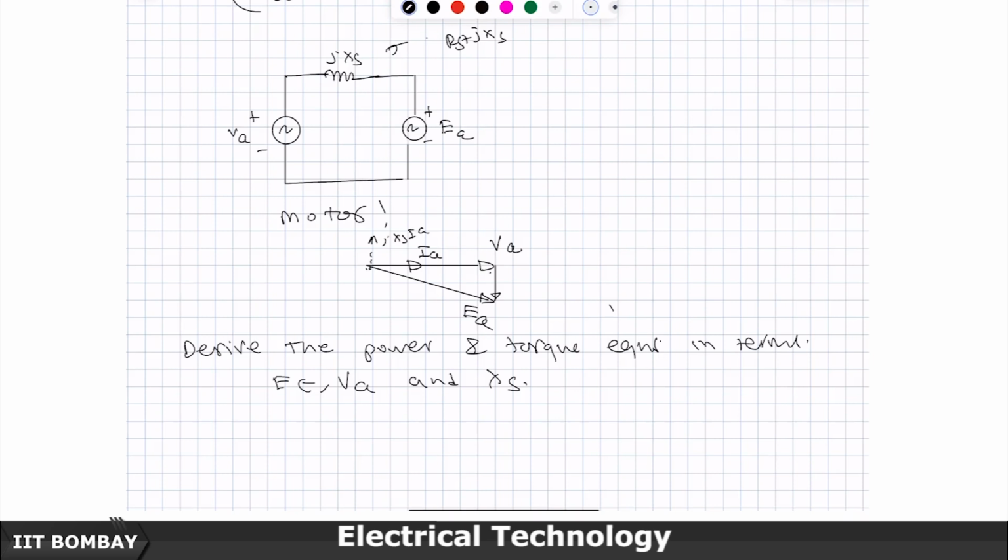So, this is a consequence of the rotor plus the reaction of the armature or stator, and hence the synchronous reactance drop j X s I A is also called the armature reaction voltage or MMF.